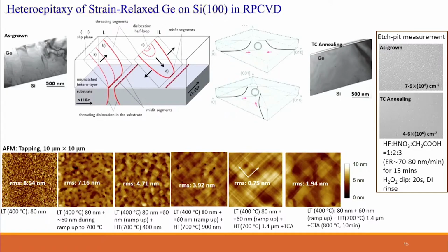This promotes the glide of this threading dislocation. So if they meet another threading dislocation with opposite Burgers vector, they pairwise cancel each other. They can also meet another on a cross plane and pairwise cancel each other. Or they can move out to the edge of the crystal and disappear. So you see that the crystal has healed so much after this cyclic annealing.